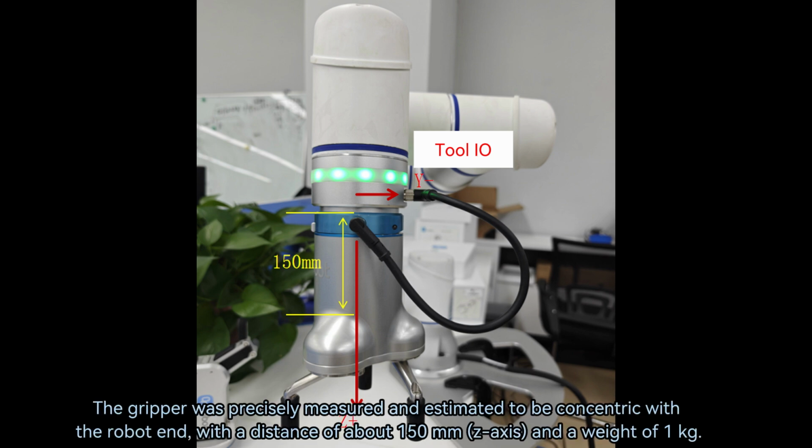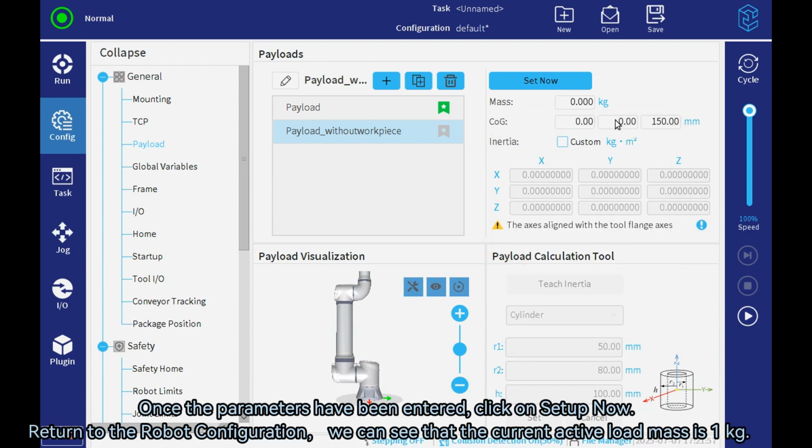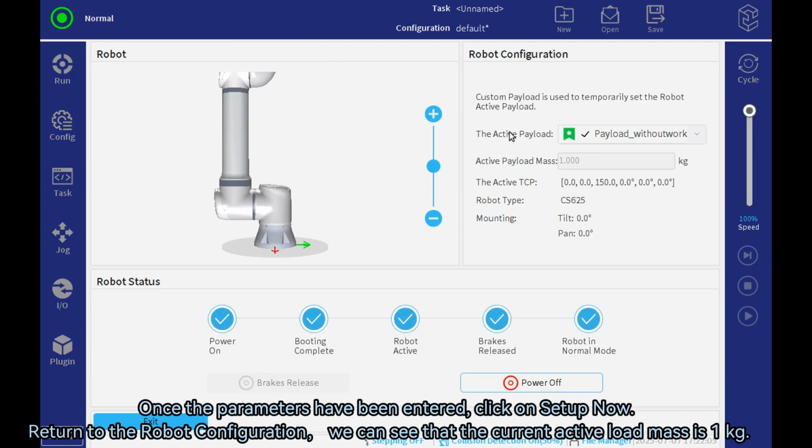The gripper was precisely measured and estimated to be concentric with the robot end, with a distance of about 150 mm on the z-axis and a weight of 1 kg. Once the parameters have been entered, click on Setup Now. Return to the robot configuration. We can see that the current active load mass is 1 kg.